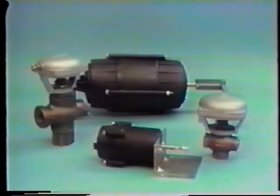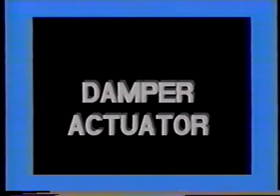Air pressure is converted to a force by utilizing a signal pressure to operate an actuator controlling a valve or damper. The valve body or damper provides the means to regulate the controlled medium. We will discuss the various damper actuators, valve actuators, and valve body configurations in this section of the presentation. First, let's take a look at the construction of a damper actuator.